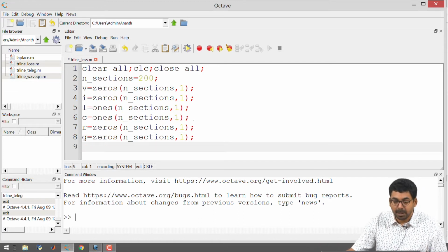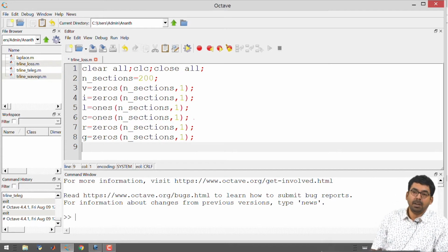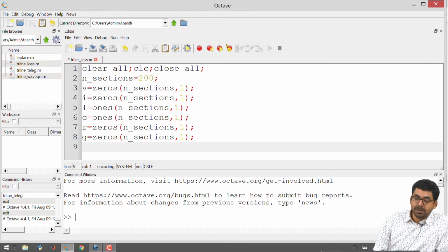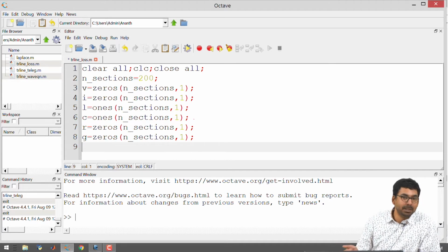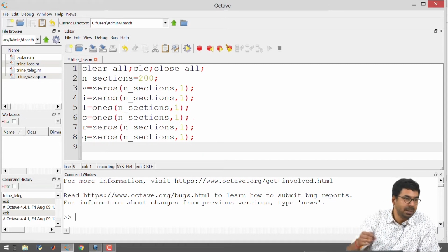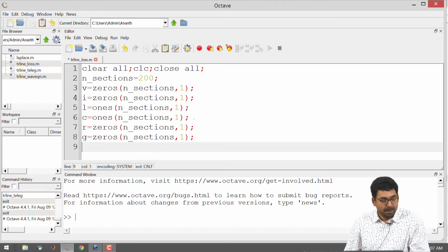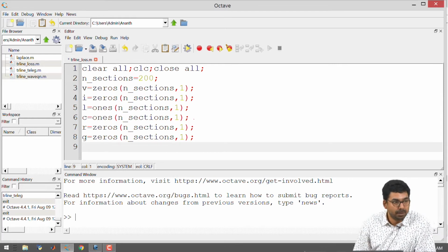So in this particular case, L and C equal to 1, so the velocity will be equal to 1 by square root of LC, which is also going to be equal to 1. So if I choose delta z to be equal to 1, delta t will automatically become equal to 1 because it has to go one space step in one time step, that is how you get the value of velocity to be equal to 1. So all the calculations become simple if I choose them to be ones. But later on accurate values can be plugged in, some considerations are needed. But this gives the essence of the theory, that is more than enough.